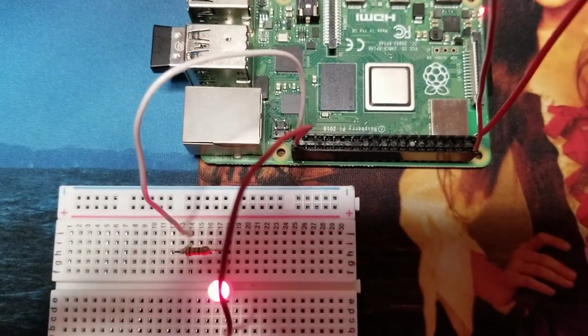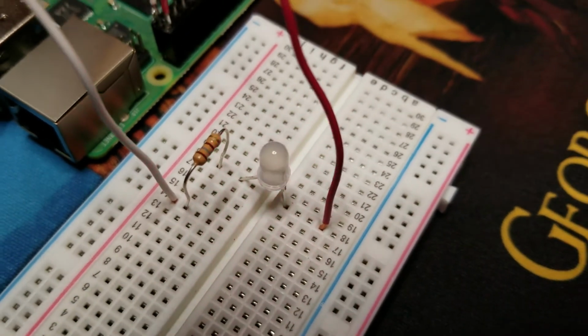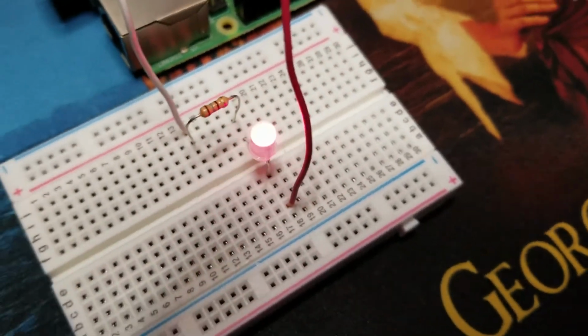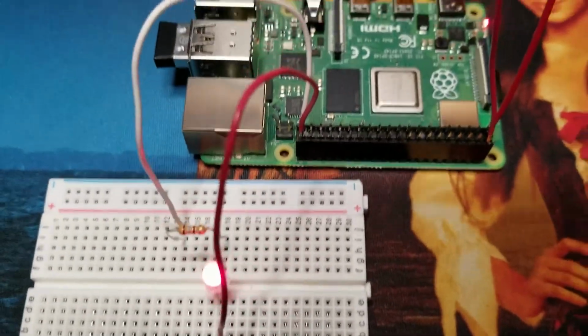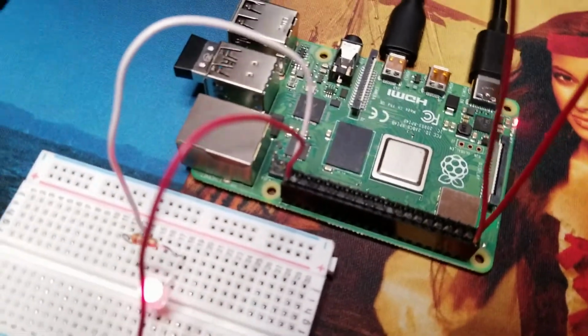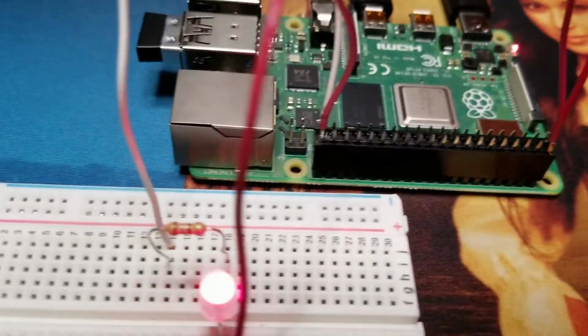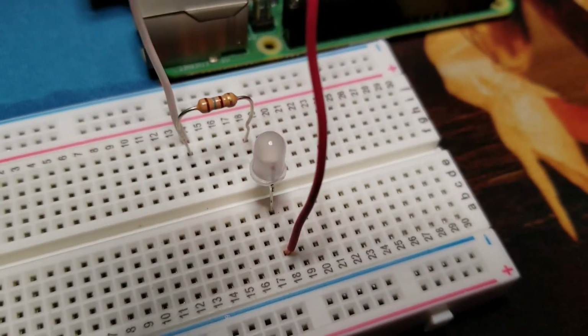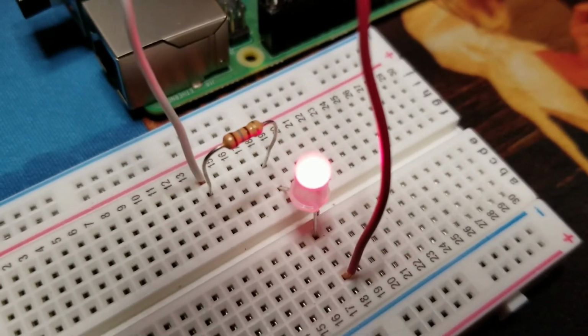Keep in mind that if you want to try running the LED at different current levels, you can try the other two resistor values that we calculated for both the 2 milliamps and the 5 milliamps, simply by changing out the 180 ohm resistor with either 260 ohms or the 650 ohms. That'll change the current through the diode. But in this example, I wanted to make it as bright as possible to make it more visible, so I used the 180 ohms and the 7.2 milliamps.